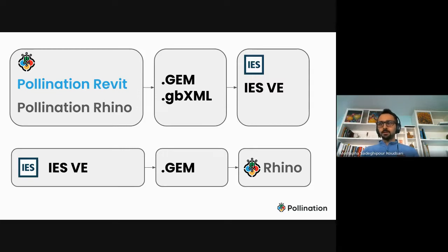If anything doesn't go through correctly, we can fix it for you quickly. Just let us know. When you go with GBXML, it has geometry and extra information. IES has a good import for GBXML when it comes to constructions and schedules. I haven't tried HVAC, but we have seen issues with geometry. There are some shade faces that IES sometimes cannot import.